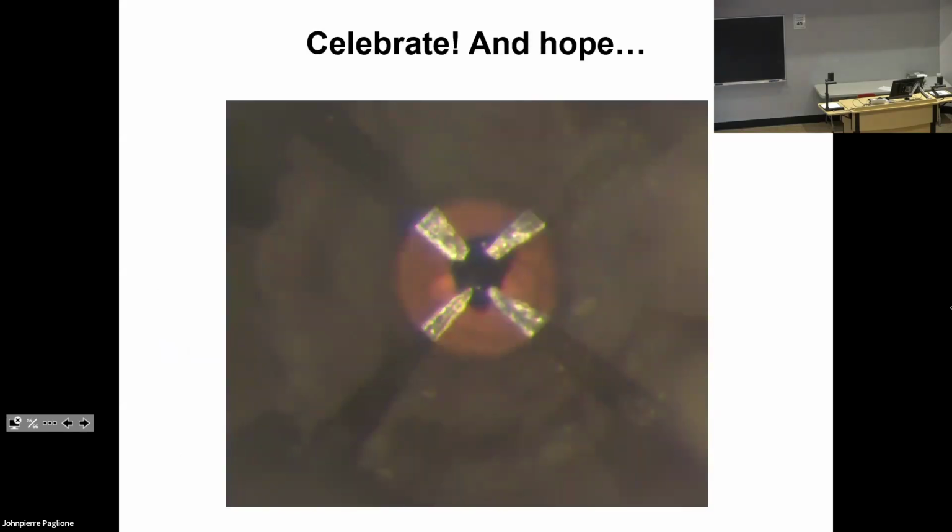All right, so that's what a final measurement or final setup might look like. This is more or less a single crystal that I put in there with my leads onto it in a van der Pauw configuration, 4-point probe, but I've seen people even do more leads for things like Hall measurements. And you can see a little bit of light coming through from behind because that's my cubic boron nitride that's past its phase transition. There's light coming from behind.